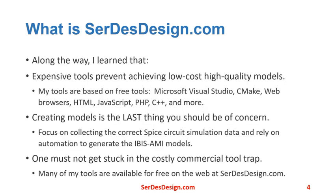Along the way, I learned that expensive tools prevent your chances of achieving low-cost, high-quality IBIS-AMI models. My tools are based on free tools: Microsoft Visual Studio, CMake, web browsers, HTML, JavaScript, and more. I learned that creating an IBIS-AMI model should be the last thing you concern yourself with. Focus on collecting the correct circuit simulation or measurement data, and use automation. My tools rely on automation to generate models from measured and simulated circuit data.